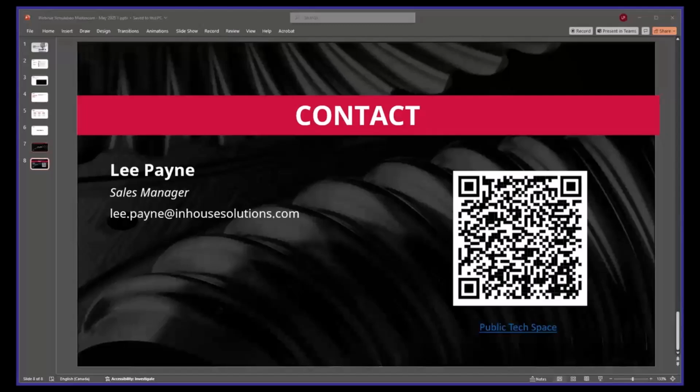Yeah. So Ryan, to answer your question, the external post is used only if you have a post processor tied to the machine simulation model that you have created. What it does is use the same post that you use for your G-code to generate the information for the simulation. So it's not reading the simulation from the G-code, but the same post will generate the information.